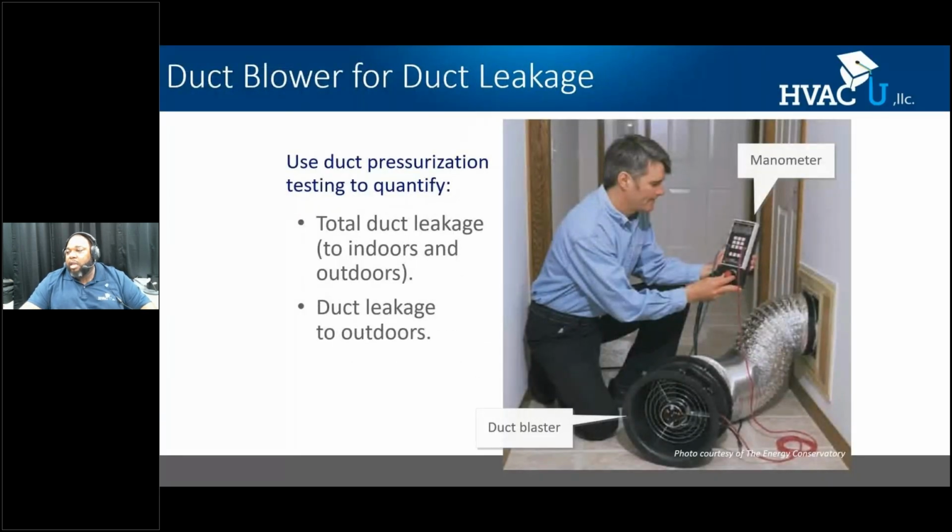And when you do that, you're going to read the leakage on the screen. This manometer speed controller is going to control this fan to 25 pascals. That 25 pascals is about what a typical duct system will run at. And the leakage provided on the screen is how much leakage this actual fan and manometer are calculating. Okay?